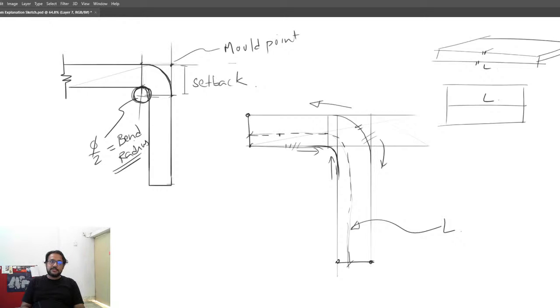Incidentally, this is the line where the stresses change from compression to extension. So let's plot the stresses at this part of the bend. Let's say this axis is compression. The highest would be at this end, lowest at this end, and on this side it will be tension. These are called bending diagrams in engineering. So you'll have this part in compression and this part in tension.